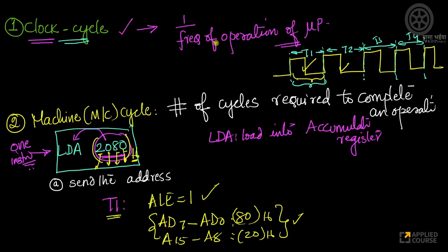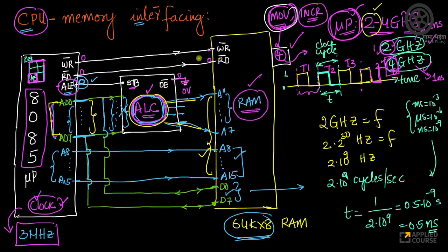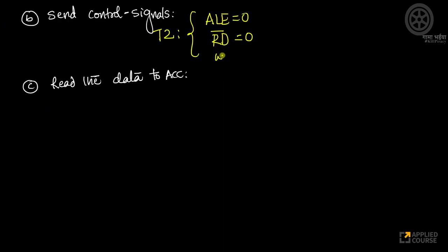Again, remember, the moment I make my read equal to 0, my RAM also will go into the read mode. When this is in read mode, I can't have write. Again, I'll also make my write go to 1 because it's also active low. WR dash equal to 1 means it's not going to write, it's only going to read. Right? The second timestamp. The second clock cycle.